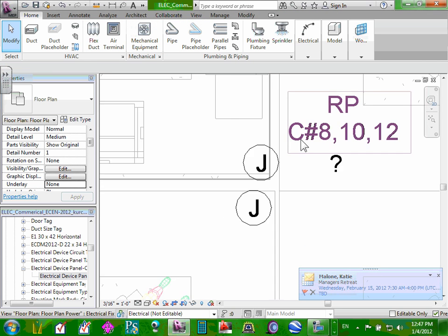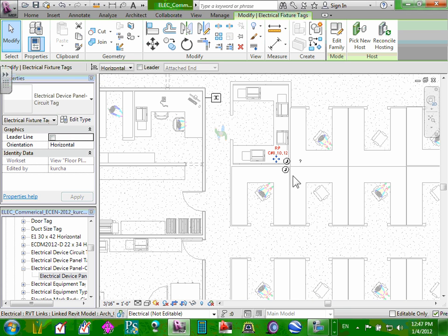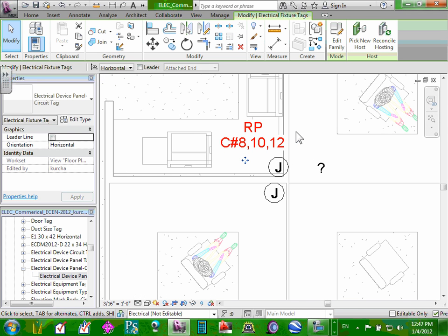So here's my first J box coming. I don't know if you can see that. When I circuited it, it assigned three adjacent even or odd circuits because it's a 3-phase circuit, 120 each with a 20 amp.